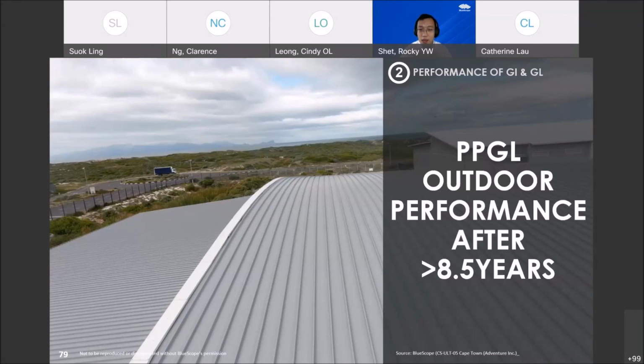All right. So are there differences between Zincalume produced by different mills for the same coating designation? Joachim, you are pointing out a really good question. Zincalume is actually a licensed technology, and there are quite a lot of licensed producers throughout the world, but there are also unlicensed producers. The difference is that the specific coating composition of 55% aluminum and 43.5% zinc from an unlicensed producer does not have the know-how per se. They might throw in the same ingredients, but the result might not be what we want for Zincalume.